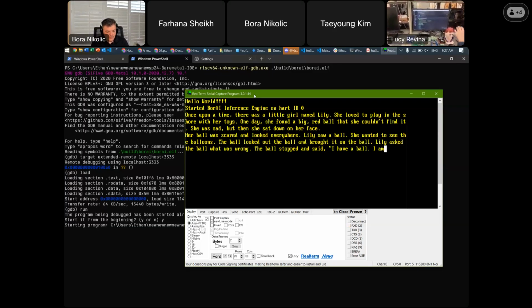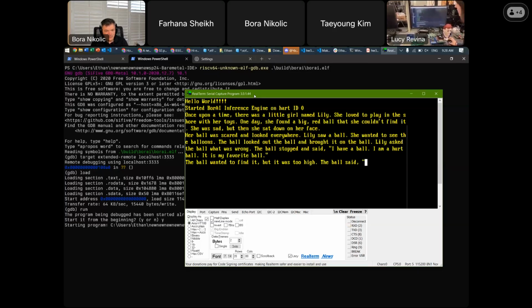So I'll go through really quickly how this works, and you see that it's pretty well automated. So it's actually a pretty short demo. You're not going to sit here for an hour and watch us take measurements. So we have some generic imports for a SciPy library, as well as some additional code that we had students write. We connect to the SMU, set some basic settings like the start voltage, end voltage, start clock and end clock. So this is pretty standard things that you would also see in industry silicon validation setups, which is a pretty helpful learning experience for students. Because we're responsible engineers, we set current and voltage limits and we set buffers and so forth. And you can see an example run here for an older measurement at 50 megahertz.